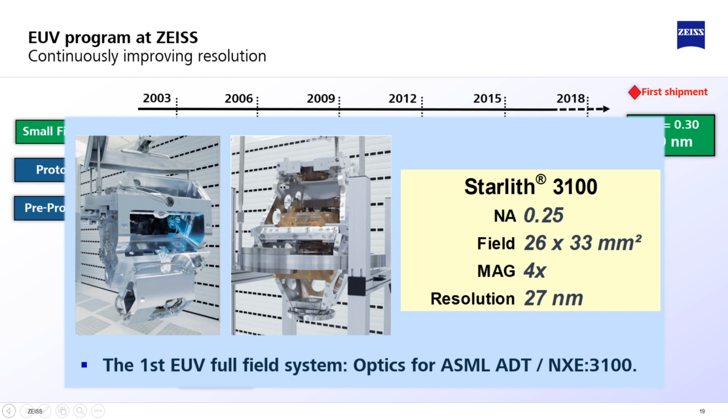As mentioned earlier, flare was originally rated as the most critical issue for EUV optics. The source of flare is scattering of EUV light from the roughness of the mirror surfaces. The alpha demo tool exhibited a flare level of 16%. This high flare level, together with the aberrations, led to concerns regarding the image contrast.